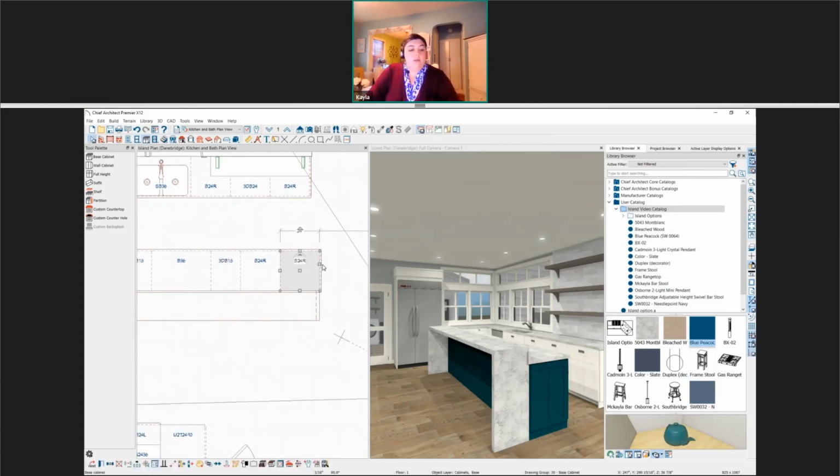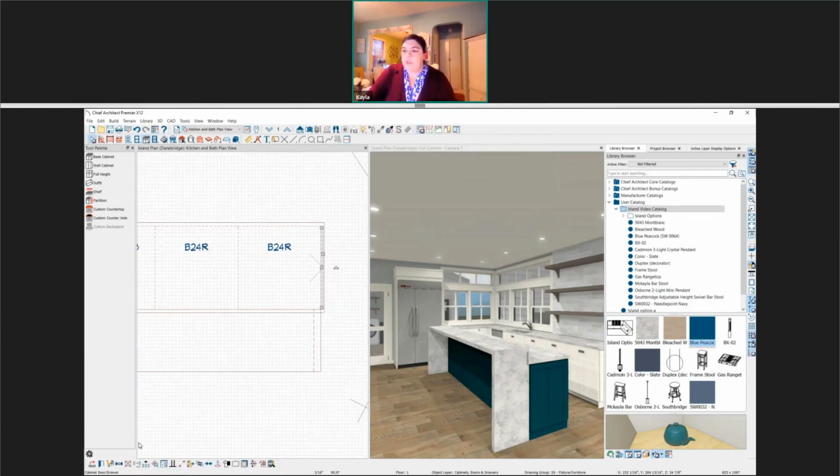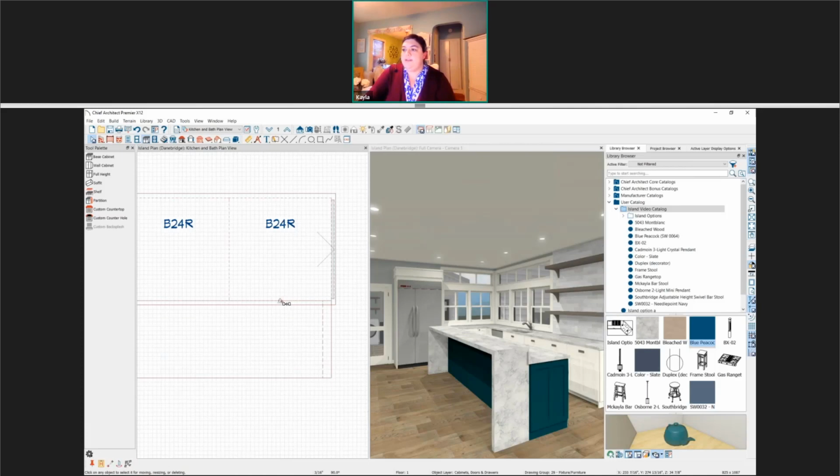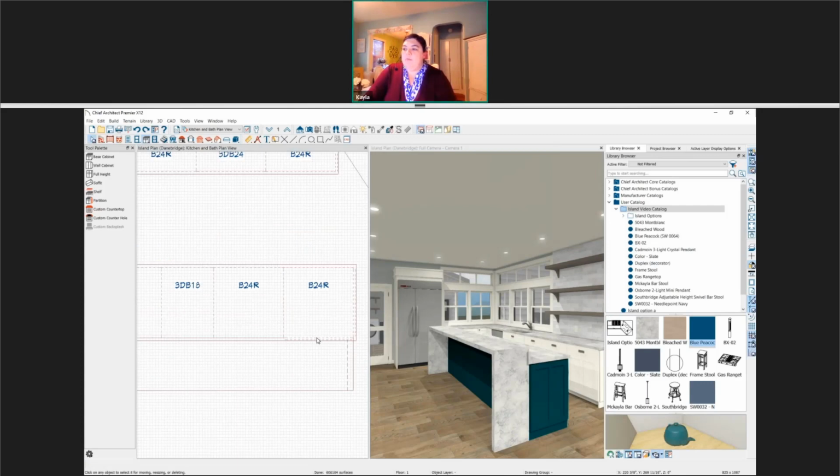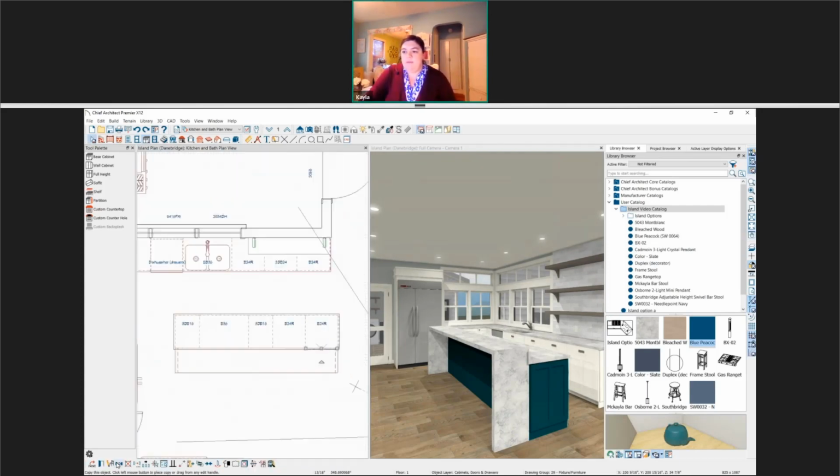So I'm going to grab this panel again, and I'm going to copy and paste it onto the back here. And then, whoops, undo that, just moved it. Control-Z is your undo. Then I'm going to grab this back panel, and I'm going to use my multiple copy. So down in the edit toolbar, we have a multiple copy option.